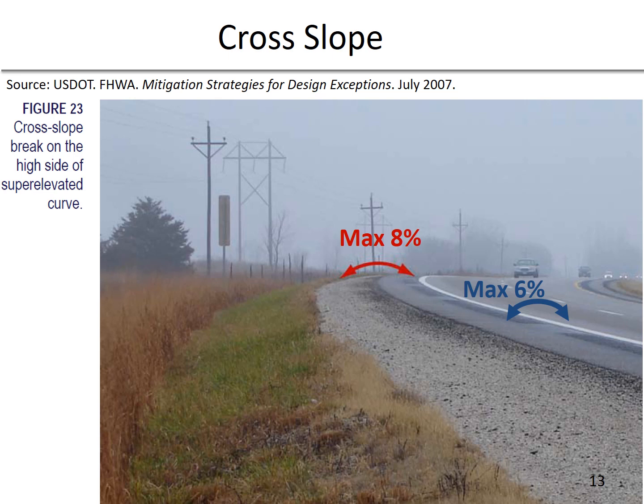Cross slopes that are too steep can cause vehicles to drift, skid laterally when braking, and become unstable when crossing over the crown to change lanes. These conditions are exacerbated by icy, snowy, or windy conditions, and both maximum and minimum criteria exist for cross slope. A formal design exception is required wherever either cannot be met. The cross slope criteria apply to typical tangent alignments also.